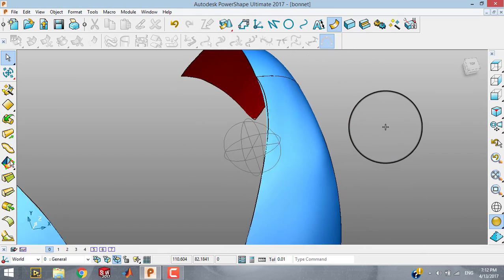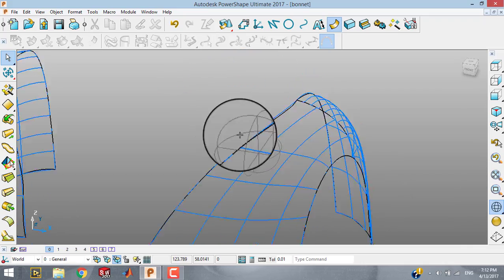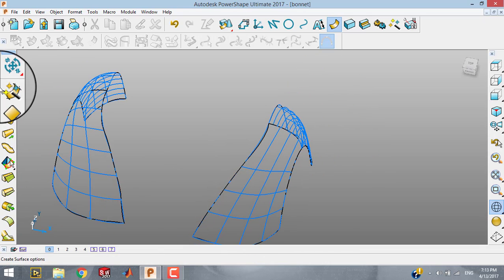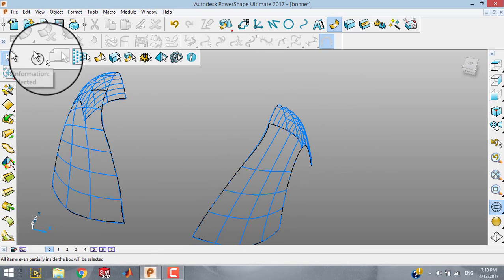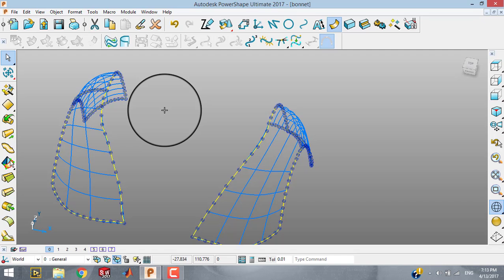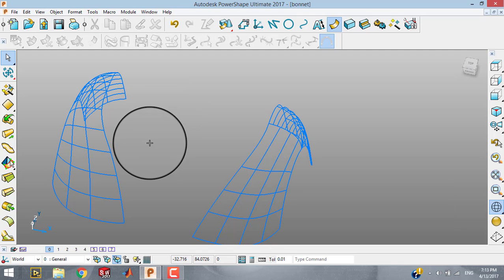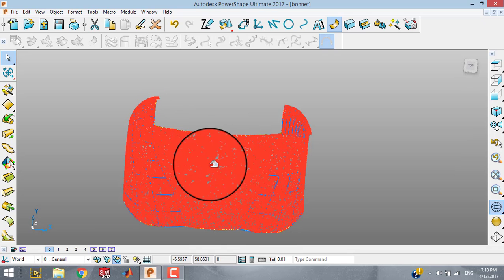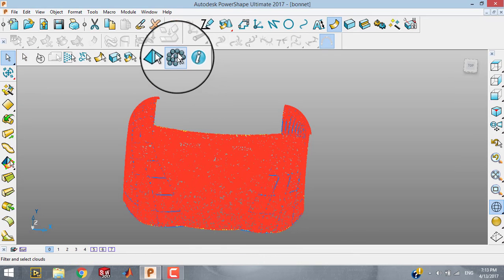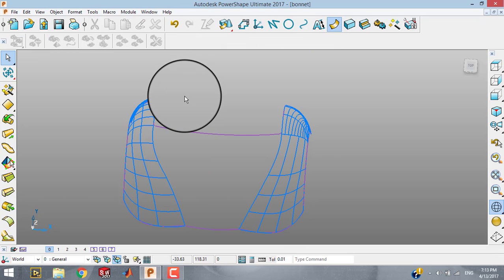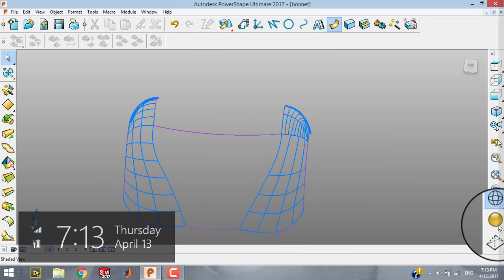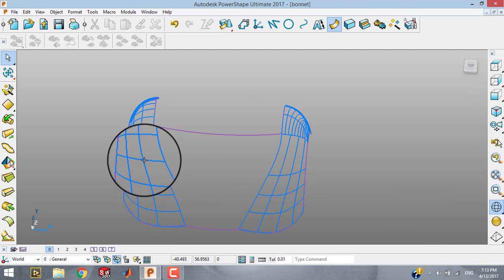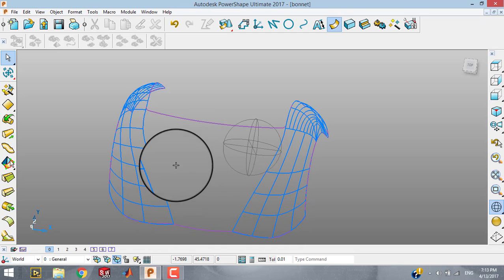Now we're gonna select wireframe, and we're going to delete or hide the curve that you created because we don't need it anymore. And now we're gonna view everything, Control L, and we're gonna hide the cloud of points. Now select the surface to view that you have a mesh on the surface, and now just select wireframe, and now we're gonna create curve just like before.